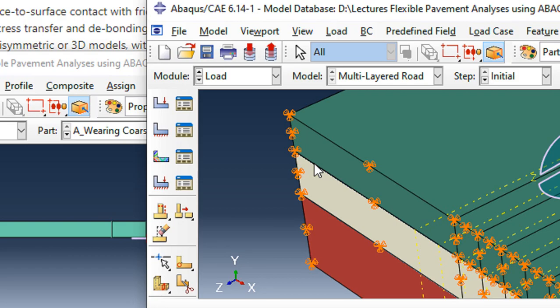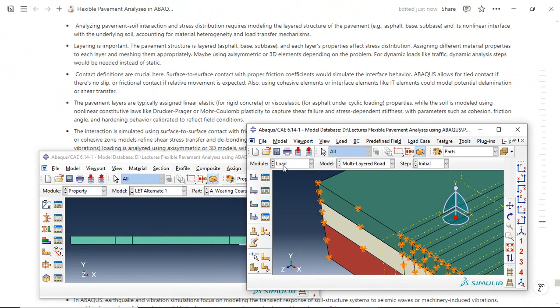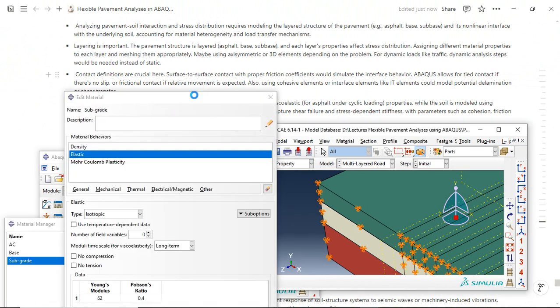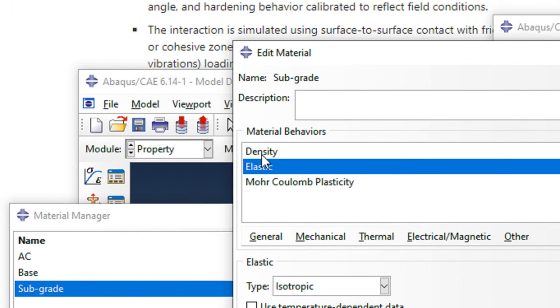Other than this, I also discussed the material models, which is important. Then the interaction is also important. If you are considering the interaction in your model, you should be careful about what you are doing. Each material model that you are modeling here will cause troubles for you if you don't understand the nature of these materials, because if your materials are soft and the loads are high, the interaction will be causing trouble for you.